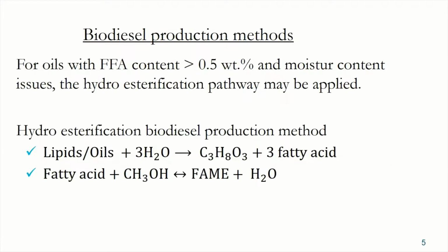Alternatively, we could utilize a so-called hydroesterification biodiesel production process. Now you have a scenario where your oils already have a high free fatty acid content. So what do you do? You hydrolyze the oil even further, completely to fatty acids, then you esterify.